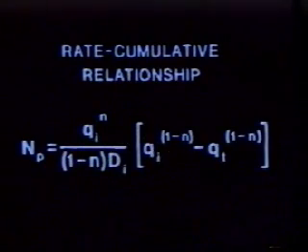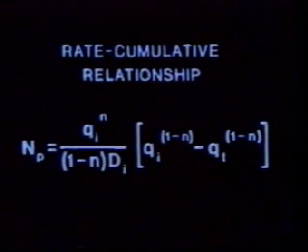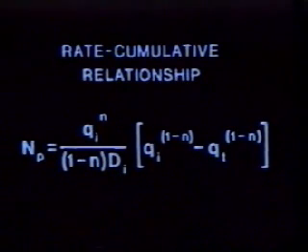In this manner, we obtain the values for capital N sub p in terms of the initial production rate, q sub i, the production rate, q sub t, at the point in time when we wish to know the cumulative production, and two constants, small n and d sub i. With these various values, it is an easy task to calculate the cumulative production, N sub p.